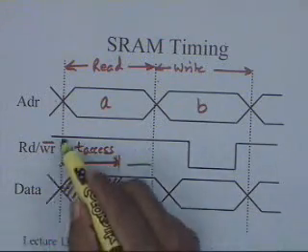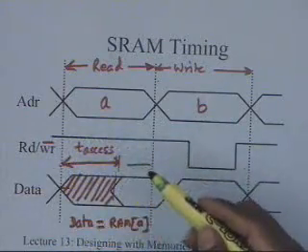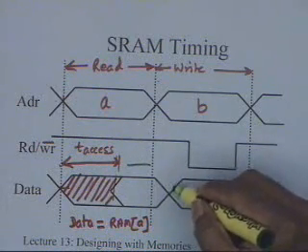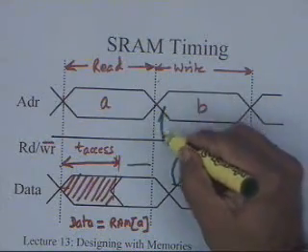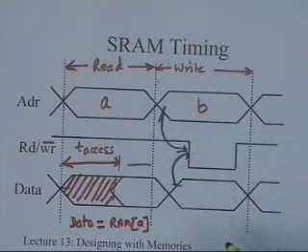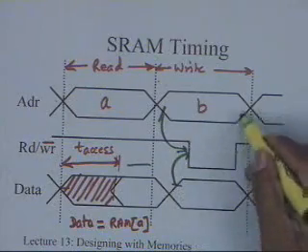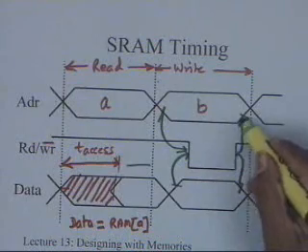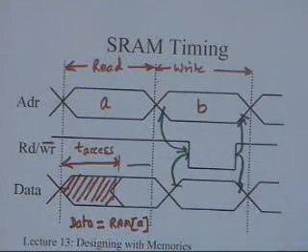Unlike the case of a read, where the signal could have been read even before and later, for this particular edge, whatever time your data stabilizes, let's say my data stabilizes here and my address stabilizes here, this particular edge, because it is going to write during this low period, should follow the stabilization of this. Similarly, it should be stable till the time this edge has come.